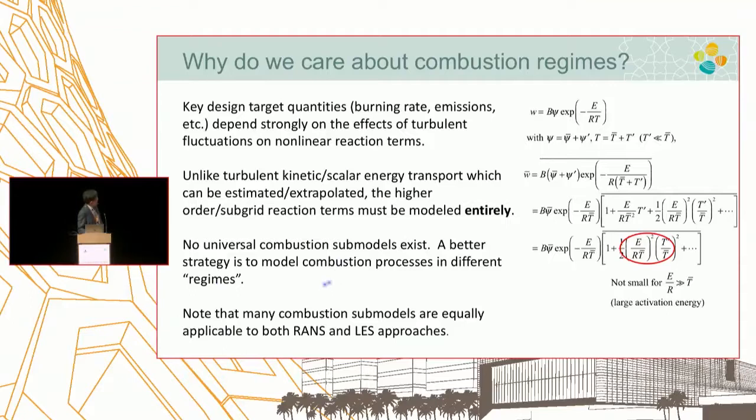And oftentimes, I will revisit that later. Because the reaction source term, this W bar, has to be modeled entirely, oftentimes the notion is still similar, even if there's a fundamental difference between RANS and LES. Again, that point I will elaborate. But the combustion modeling concept is still shared in common, with some minor adjustments to ensure consistency.